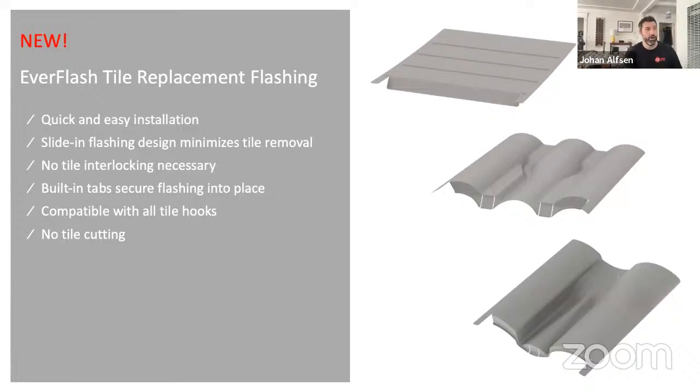tile flashings. So as I mentioned, the tile manufacturers have standardized on these concrete tiles, and the shapes of these tiles are pretty standard across the board, which gives us a huge advantage to creating replacement tile flashings that allow you to completely remove the tile, because grinding down the tiles for the hook pass through tends to be a little bit messy. There's some OSHA safety requirements where you have to wear a mask, you have to have a cutting station, a dust collection system. It just became a lot more cumbersome.